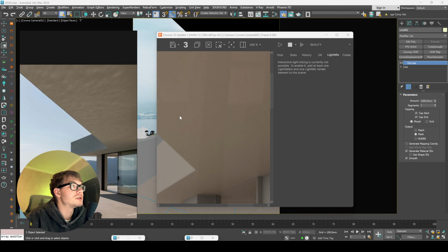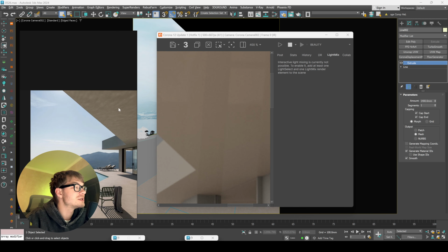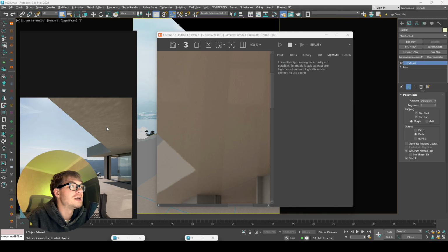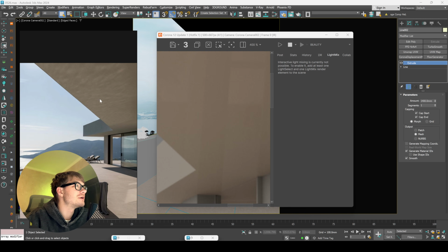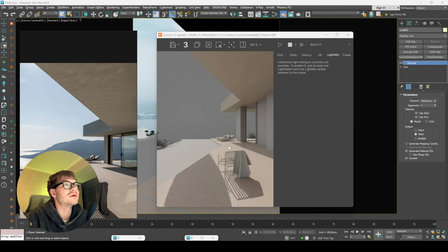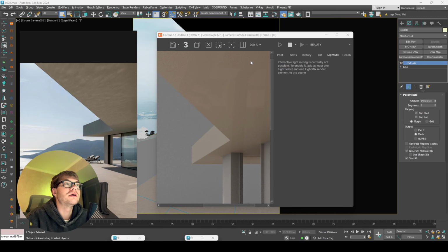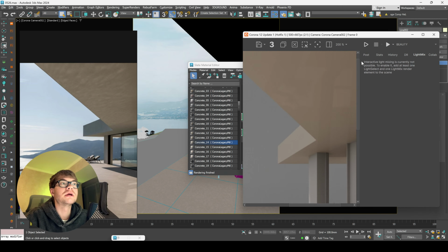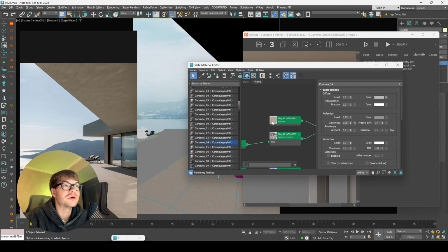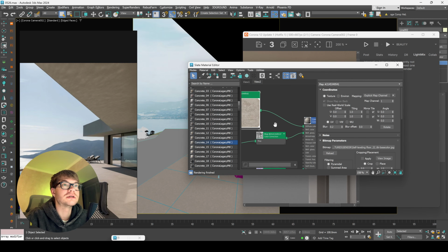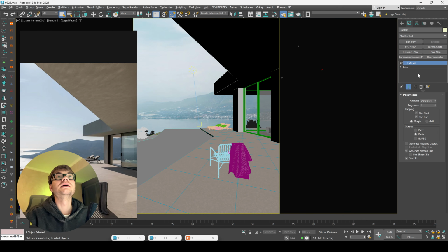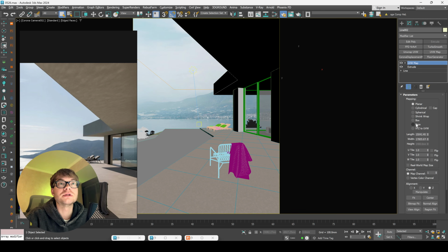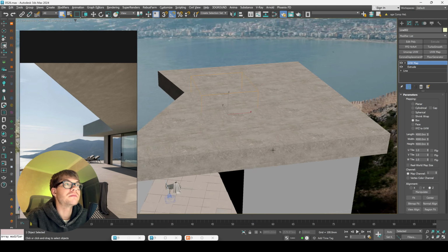So here it's darker and it also reflects some kind of the reflection from the water on the pool. So here we can edit our material. I think we need to find something more rough or set this material the right way. All right, let's apply UVW map. Here I usually use 4000 on 4000 millimeters mapping. It will look like this.